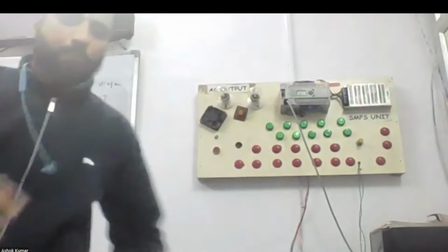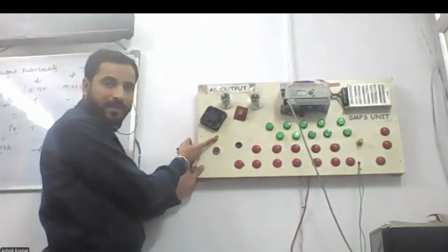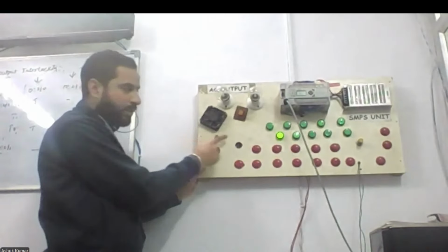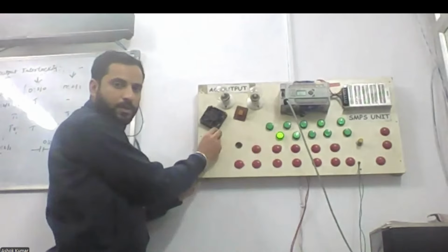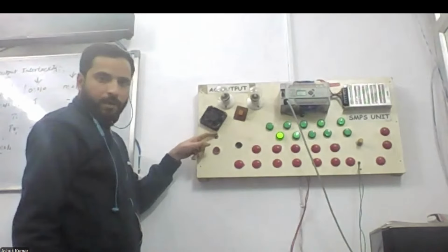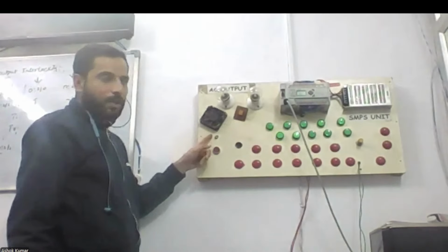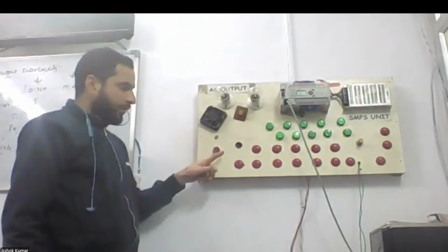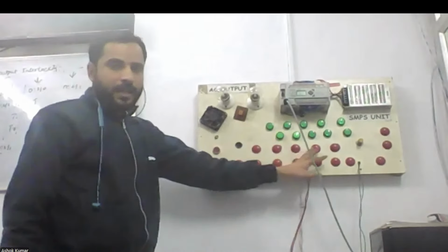I need to check the output I was showing you. So we have created the program; I colon 0.0 slash 0 is on. The output is on. If I off it, the output is off. If I on it, on. If I off it, the output is off. So this one is the toggle input. Okay. This one is NC and the rest are all NOs.